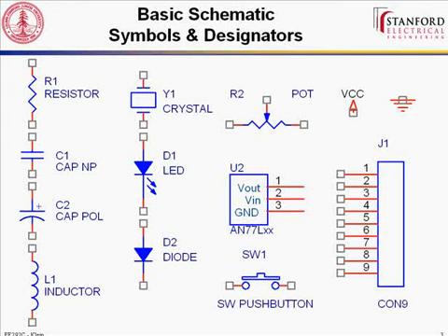When you replace crystal, do you use the frequency of the oscillator or the part number? All right, so the question is, what would you do with crystal? Typically, you'd put the frequency, although sometimes you'll put a specific part number if that's what you really care about. For example, on LEDs, you may indicate the color, or you may give a specific part number. It's kind of up to you. Generally, you'll keep it a bit more generic, and then have the part number explicitly called out later on. However, with integrated circuits, you usually put the part number, because that is what the chip is.